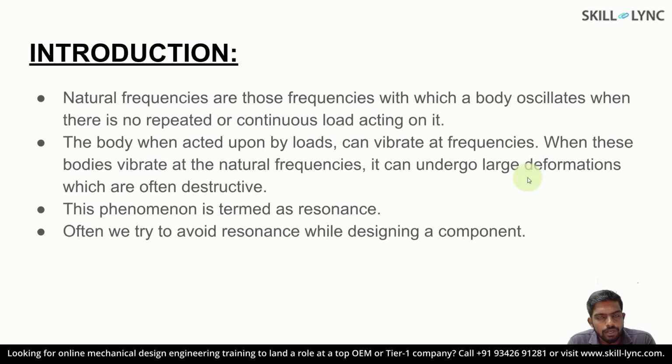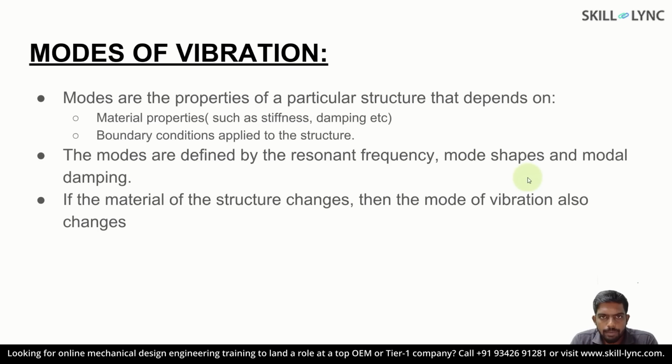This particular phenomenon is called resonance, wherein the frequency of the motion of a part matches its natural frequency. The amplitude multiplies, thus resulting in resonance. So it's very crucial to perform a frequency analysis on any part before using it in any mechanical system. A material vibrating at its natural frequency has a tendency to displace in any direction. This tendency is studied by looking at the mode shapes at the vibrating frequencies.